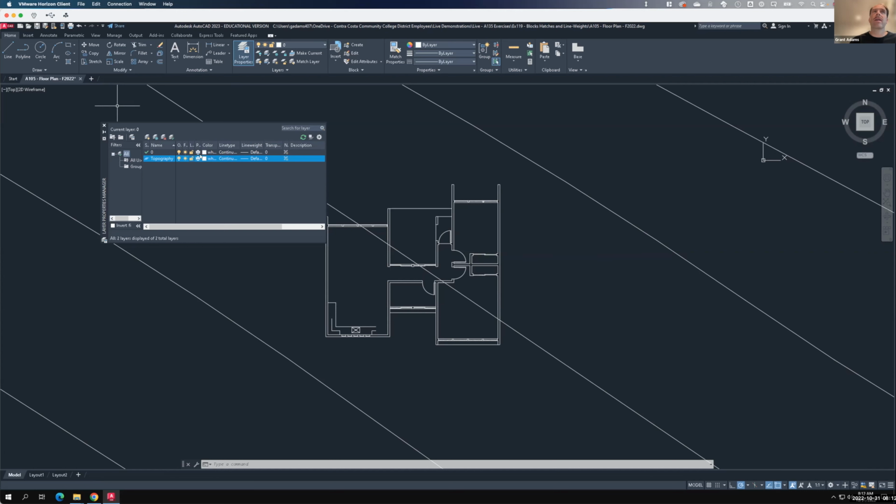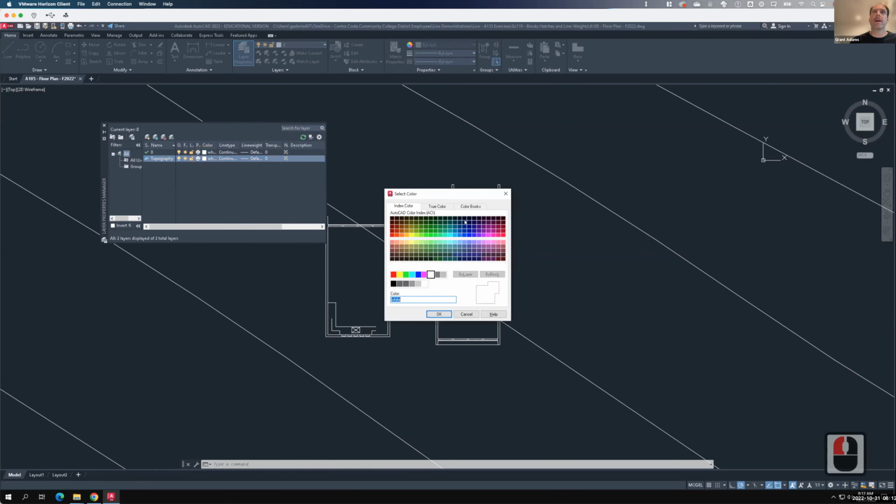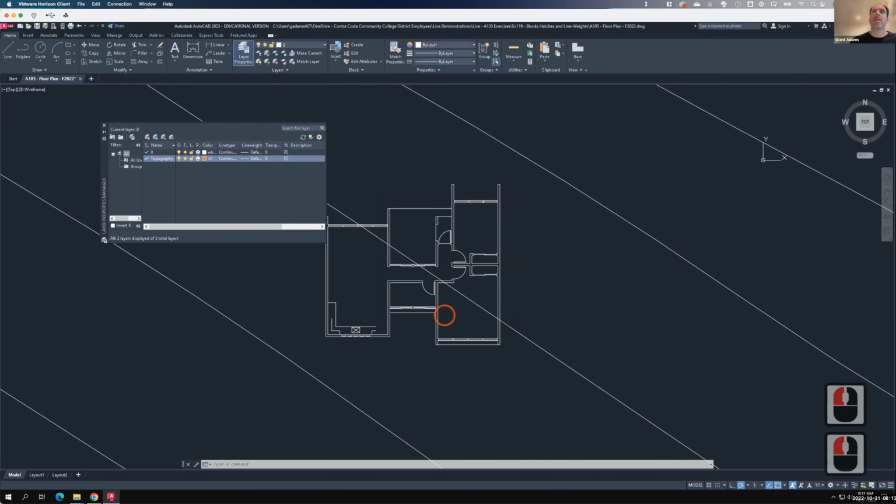Next up, we have the layer color. So the layer color, which is currently white, right? When I go to print, will turn black. However, I can pick any other number of colors. And you can see here, we have an AutoCAD color index where we can pick any one of the colors. If I were to pick a color, let's say this orange, for example, and say okay, all of my topo lines would turn orange. Now, sometimes people like to draw in colors so that they can see different lines standing out against other lines, and you can tell what object is on a layer.